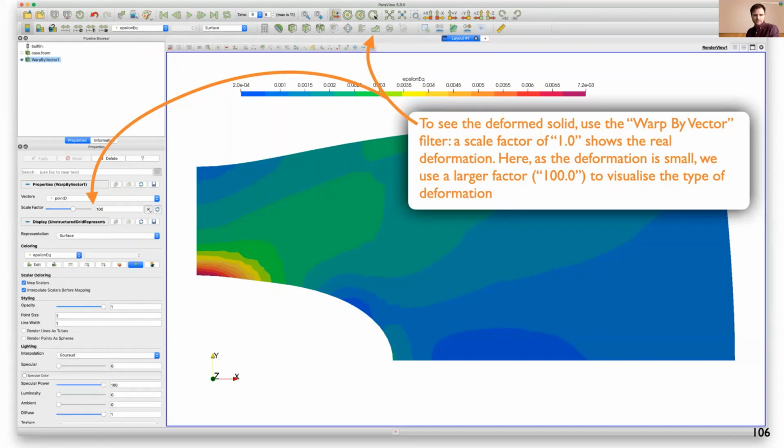So here's another question. Can a moving distributed load be modeled? There are a number of boundary conditions available. Is there a moving distributed load? I'm not sure if one is implemented. I know you could use Groovy to modify one of the existing load boundary conditions, though it wouldn't be that difficult to write your own boundary condition. So if that is something you want, it's not that difficult to do. You can always contact me afterwards, or we can do it by just posting on the forum, and we can discuss it there. But you could use Groovy. GroovyBC will let you do it as well.